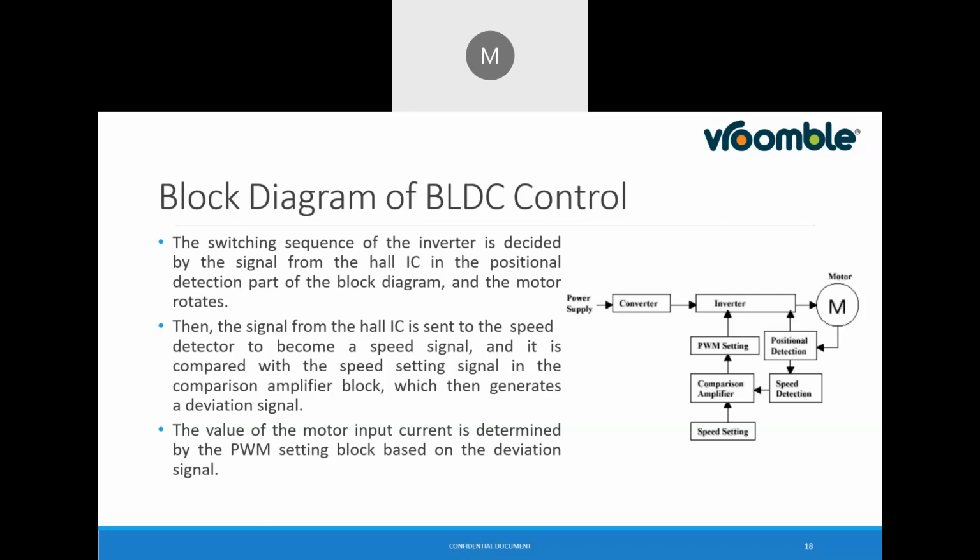Now the switching sequence of the inverter is decided by the signal from the Hall ICs in the positional detection, as shown in the block diagram, right?